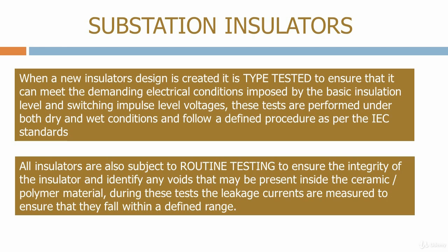All insulators are also subject to routine testing to ensure the integrity of the insulator and identify any voids that may be present inside the ceramic or polymer material. During these tests, the leakage currents are measured to ensure that they fall within a defined range.